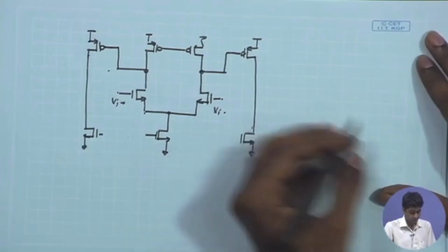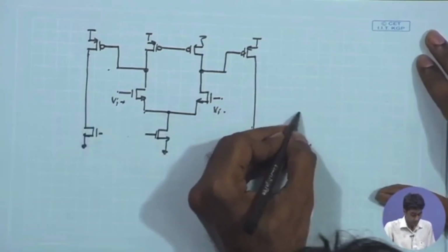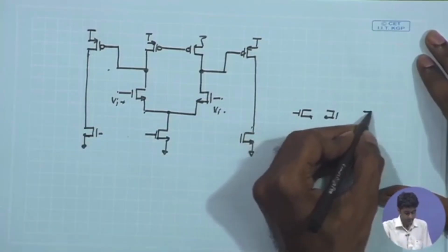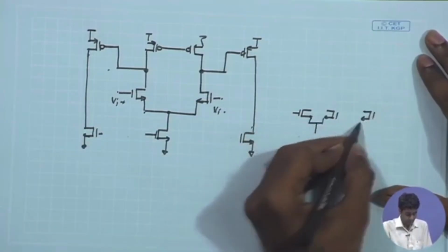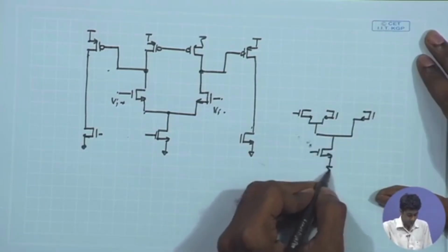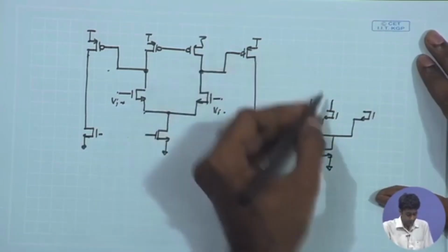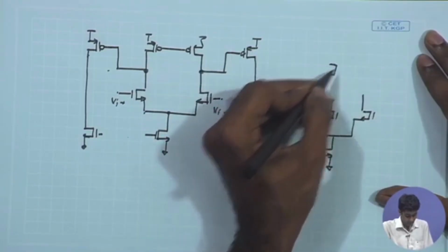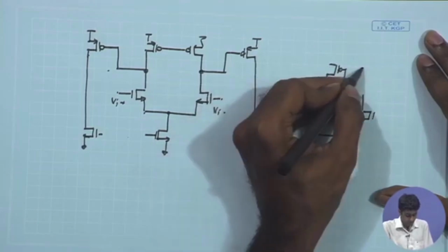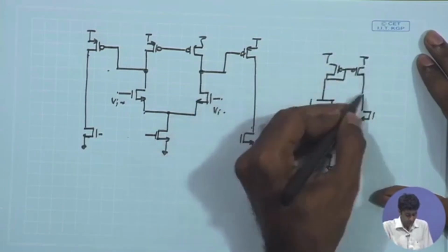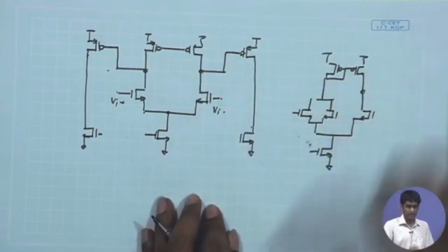Now, for the first stage, we can build the error amplifier that we discussed in our earlier sessions with a split input pair, extracting the common mode voltage over here, and the output having an overall current mirror load, which gives us a sufficiently high gain from the error amplifier.